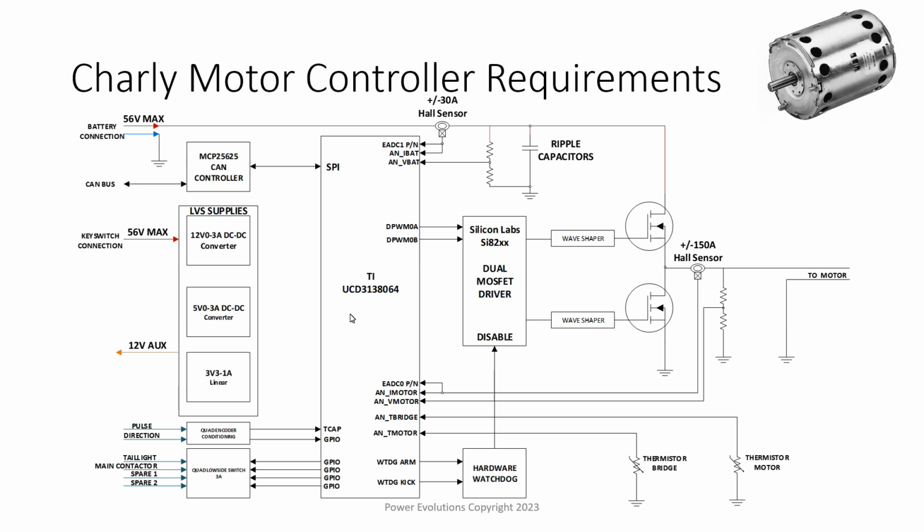And because it isn't designed for this, I'm not 100% sure that it will work the way I want it to work. I know this thing will work fine in a motoring situation, but when we start stacking loops, you want to be stacking the battery loop with the motor control loop, so that when one limit is reached, it limits the full current output of the controller.